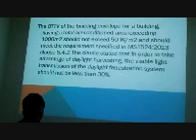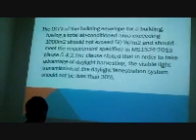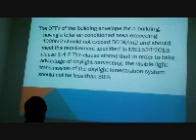And the OTTV of the building envelope for a building having a total air conditioned area exceeding 1000 meters squared should not exceed 50 W per meter squared, and should meet the requirements specified in MS 1524:2013 clause 5.4.2. The clause stated that in order to take advantage of daylight harvesting, the visible light transmission of the daylight fenestration system should not be less than 50%.